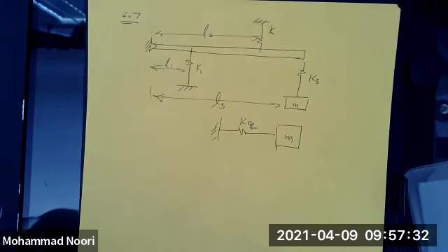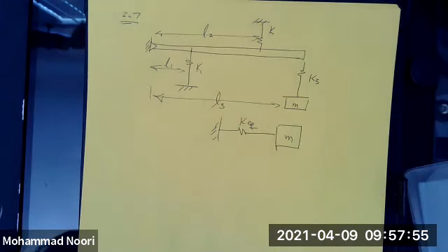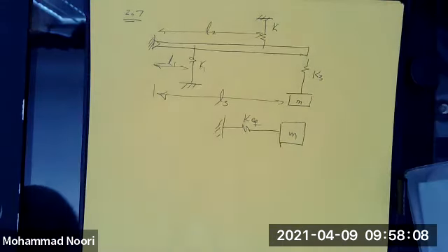If you have several forces acting on a system, you can find a force, and you can move these forces to any point you want, right? As long as the moment that the sum of these forces that you put at that point generates about a point is the same as the sum of the moments of those individual forces about the same point. This was the concept of equivalent system. So we're going to use that concept.